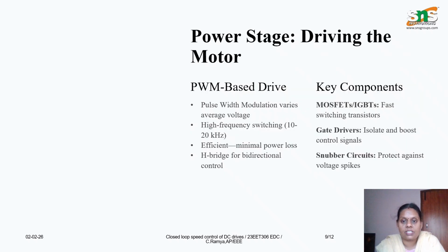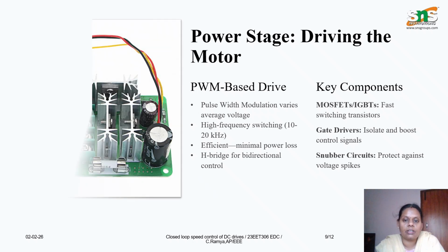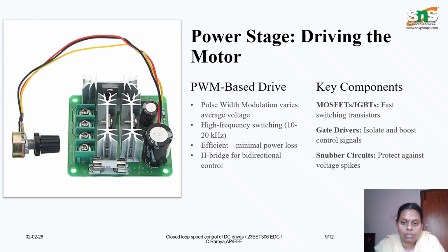And we have the power stages, which are the driving part. Here the controller output is not directly applied to the motor; it goes to the PWM-based motor drives. We are dealing with duty cycles, and the switching frequencies are very high, around 10 to 20 kilohertz.